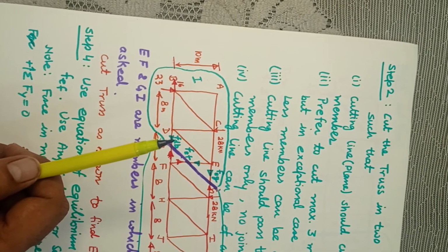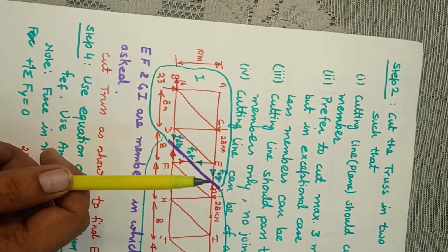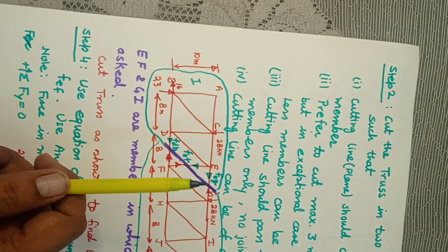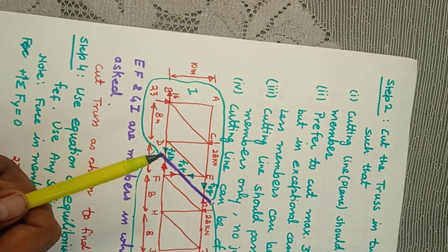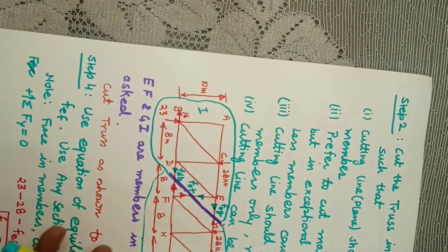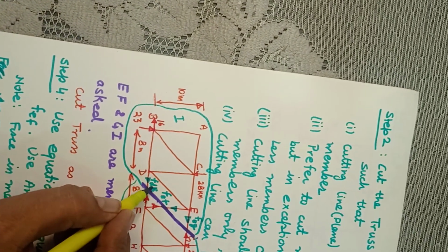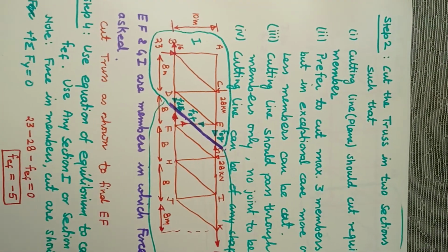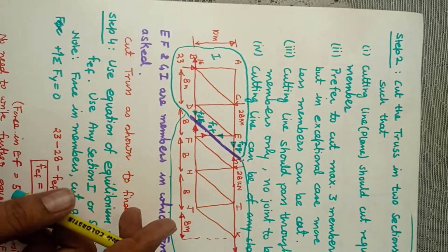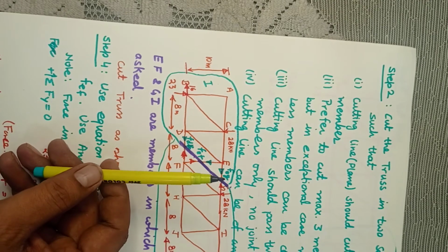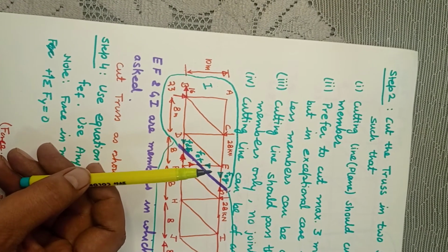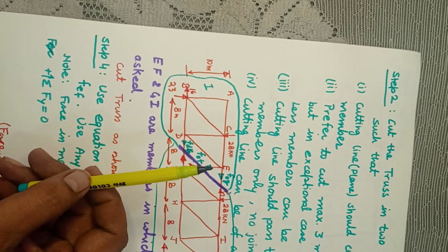And the forces in the members which we have cut, so FEG, FEF, FDF. So this is basically as we have done in the conventional method, that is method of joints. So force at E because of G is known as FEG, and we have taken all these forces away from the joint.